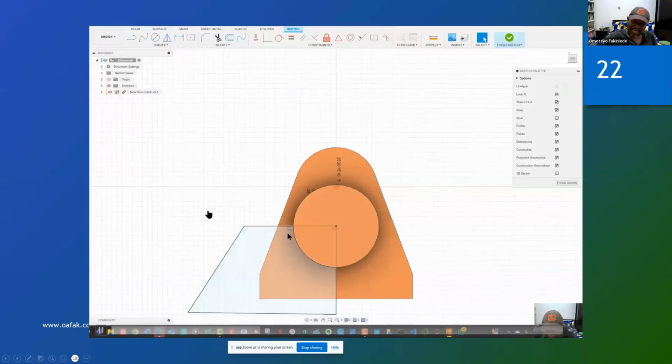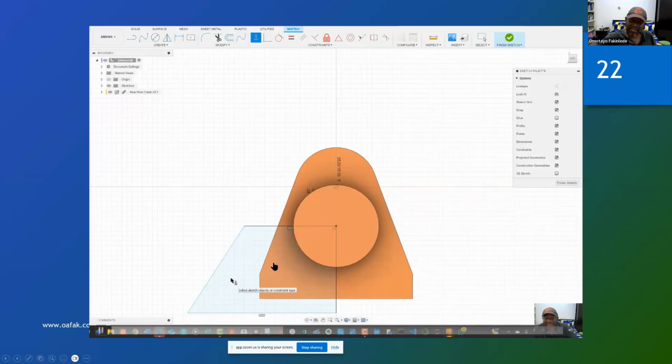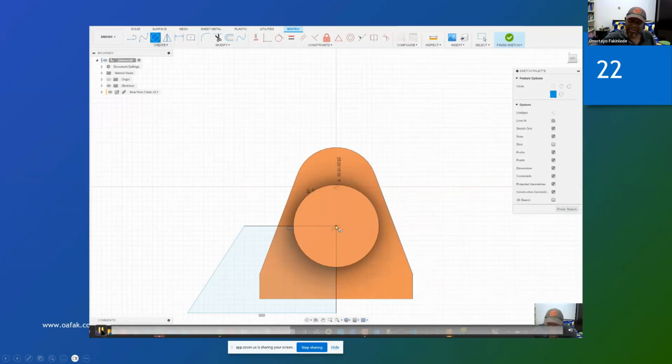Then we can make sure that that line is horizontal, it's already horizontal. There's a sign there showing, and a right angle there showing that it is vertical. We can force the other line to be horizontal by taking our horizontal vertical constraining tool. Once we choose that, that is horizontal. If we try to put it there again, it tells us it's over constrained because that's already vertical. There's nothing to do. So that is it. If you look again after finishing the sketch, you will see that it is in the correct place. So you can go and click finish sketch.